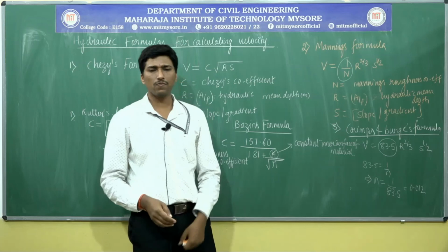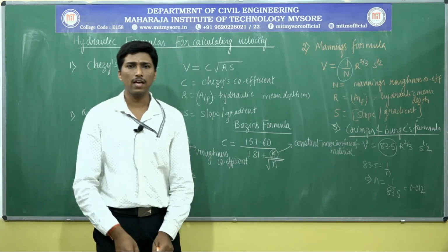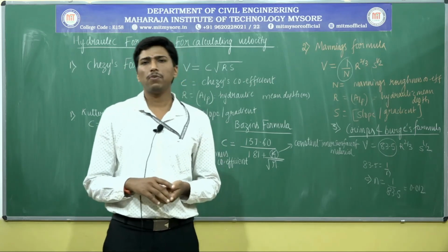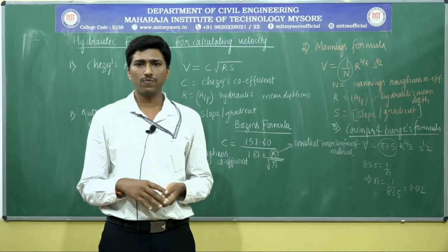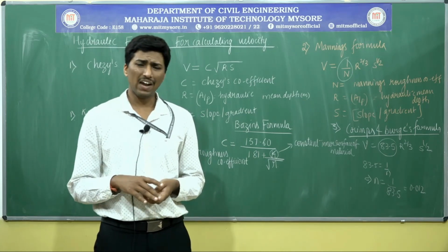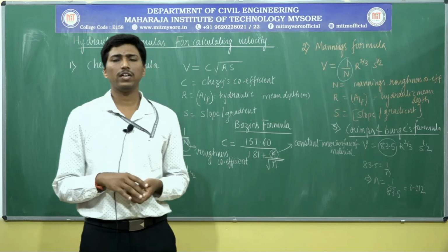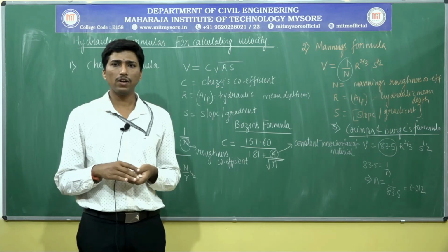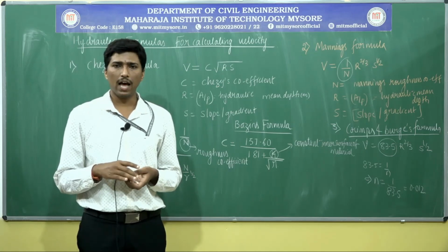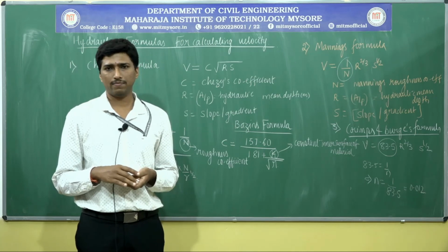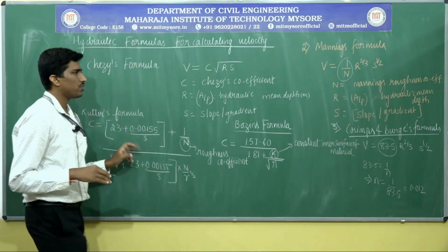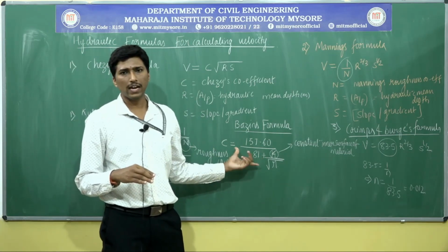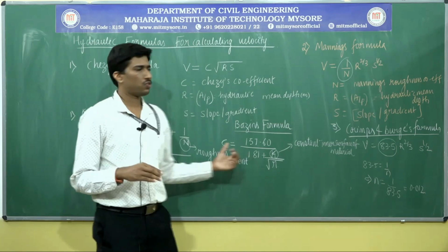See, in the development of any engineering aspects or any mathematical principles applied there, there will be certain modifications. We call them modified equations. We have the Hazen-Williams equation also, and we also have another set of equations we call the modified Hazen-Williams formulas. This kind of modification is mainly made according to the experimental results they have obtained and verified in an empirical manner. That is why these values keep on changing from one to another. They do not remain the same, based upon what kind of relationship they have established.